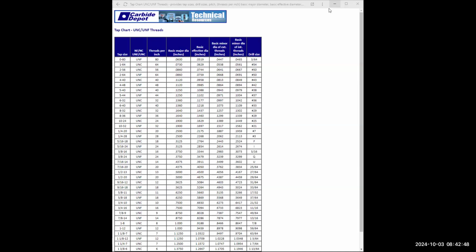So we have our circles laid out here. We don't need these lines anymore. So I'm going to type in the letter E, enter, and I'm going to click on these lines. Enter. Now, hopefully you have something that looks like this.